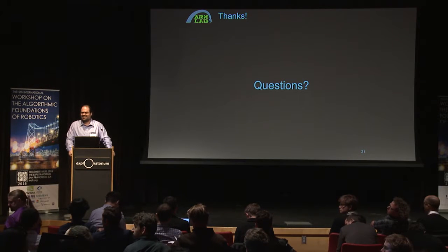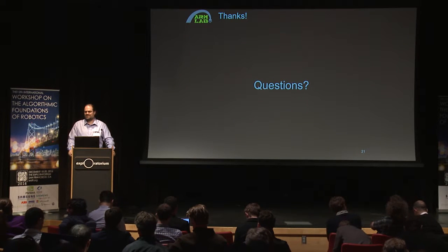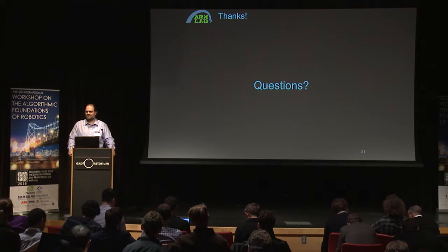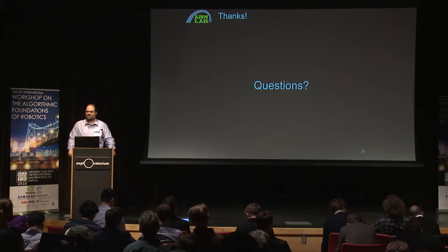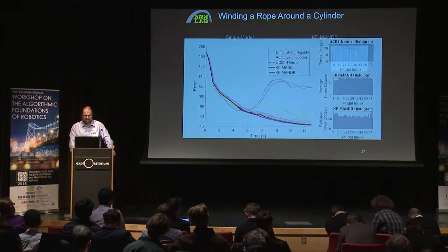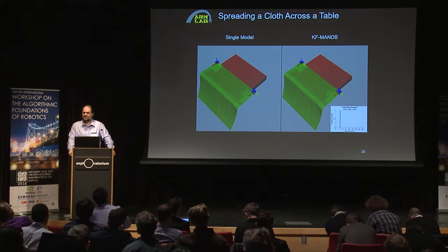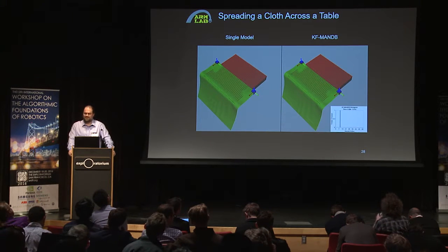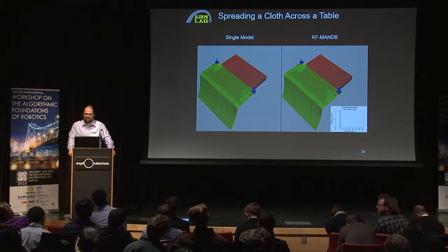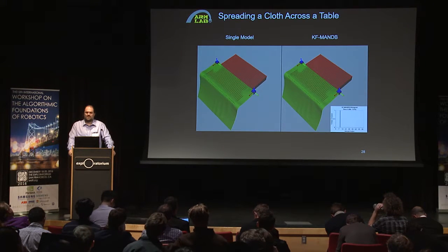Really nice work. I think the problem of dealing with deformable objects in motion planning is really hard, and part of it is the aspect that we don't have good single models to plan around. So what I'm curious about is a little bit more about the dynamics when you add more and more dynamics in these scenarios. So you had the case of essentially putting this tablecloth over the objects. And another technique that people might use in that circumstance is to take both of the corners, throw it through the air, and then let the whole tablecloth settle on the table rather than dragging it across. And that would require much more of a deeper knowledge of the dynamics. And so what I'm wondering is, with an approach like this, can you run it in a closed loop at faster rates to try to handle those? Or do you need other sorts of extensions to handle those sorts of situations?